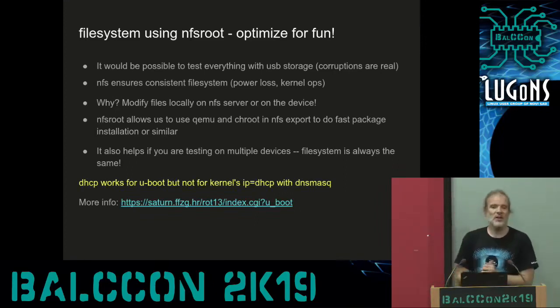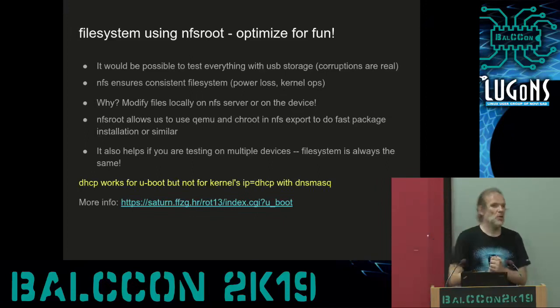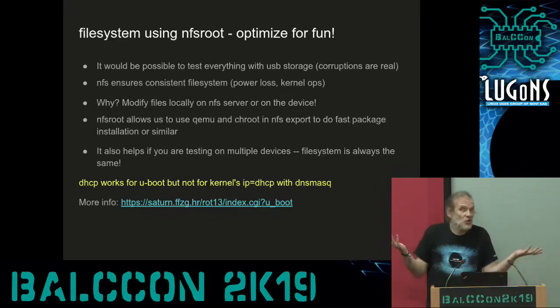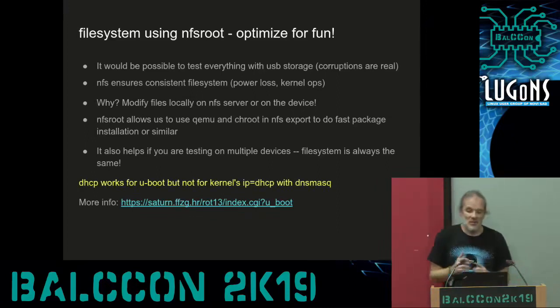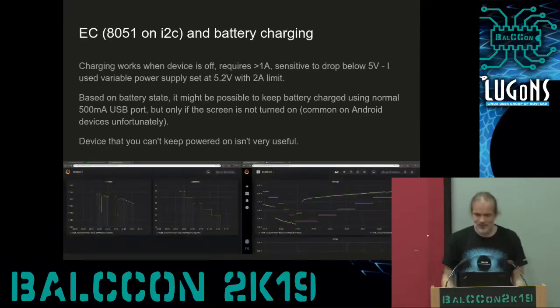Also, word of warning, for me, U-boot would happily take the IP address and DNS mask over DHCP, but the kernel wouldn't. So the command line option ip=dhcp, which should work in the kernel, actually doesn't, but you can hard code the IP and that's okay.